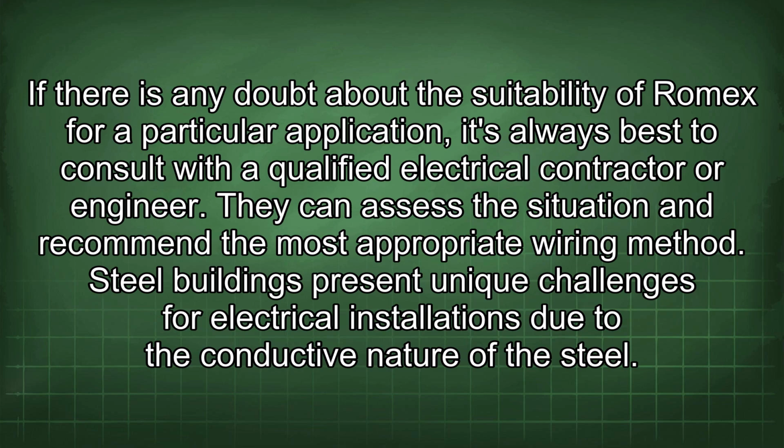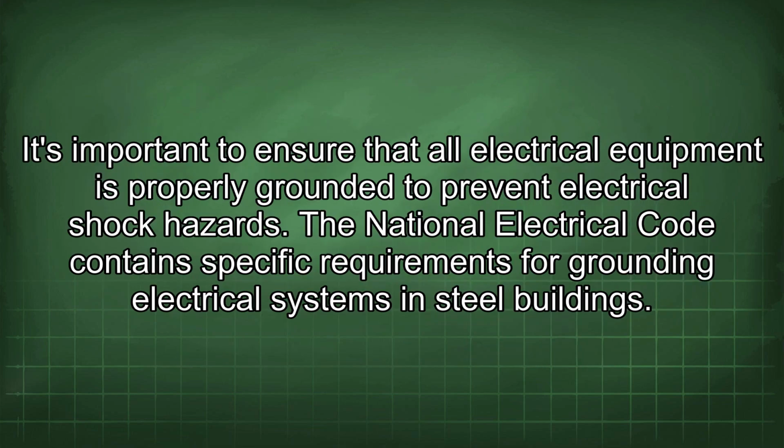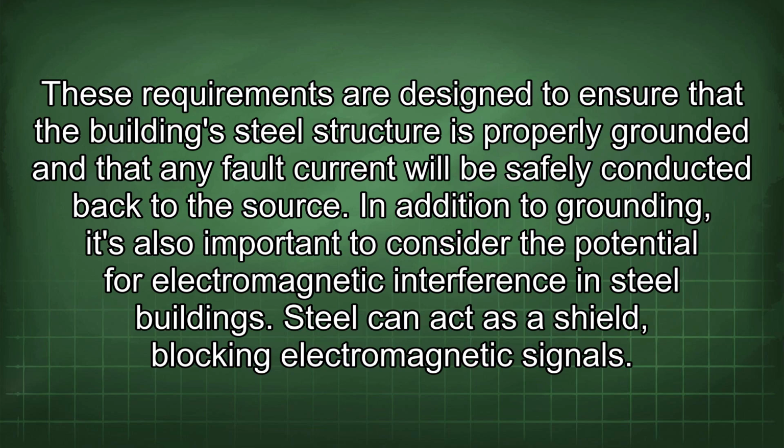Steel buildings present unique challenges for electrical installations due to the conductive nature of the steel. It's important to ensure that all electrical equipment is properly grounded to prevent electrical shock hazards. The National Electrical Code contains specific requirements for grounding electrical systems in steel buildings. These requirements are designed to ensure that the building's steel structure is properly grounded and that any fault current will be safely conducted back to the source.